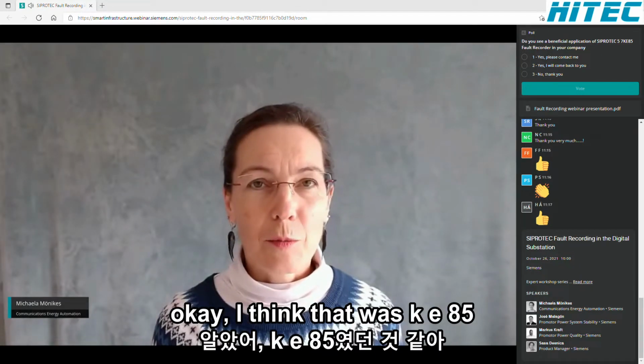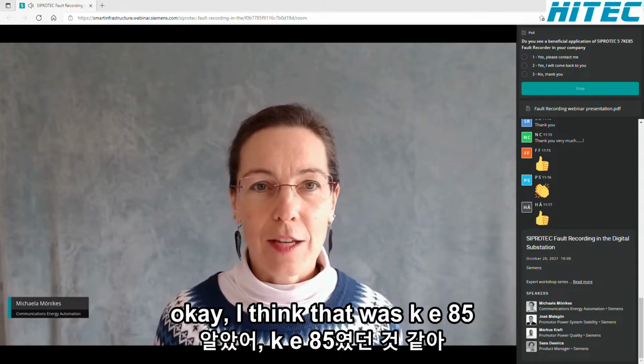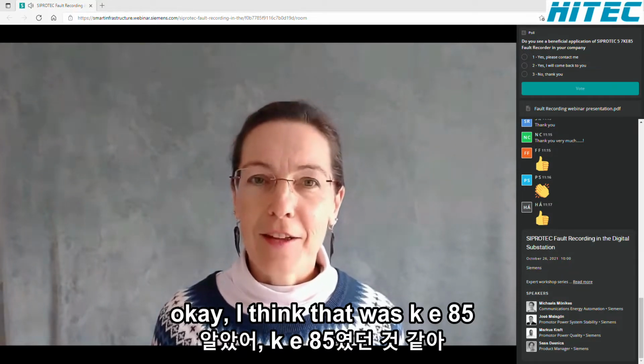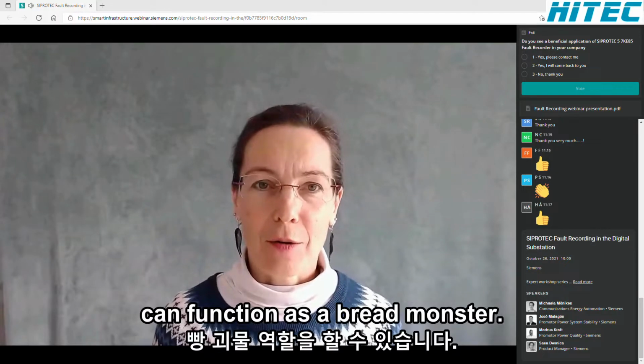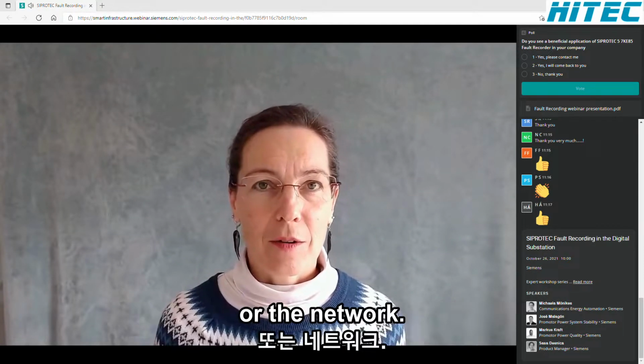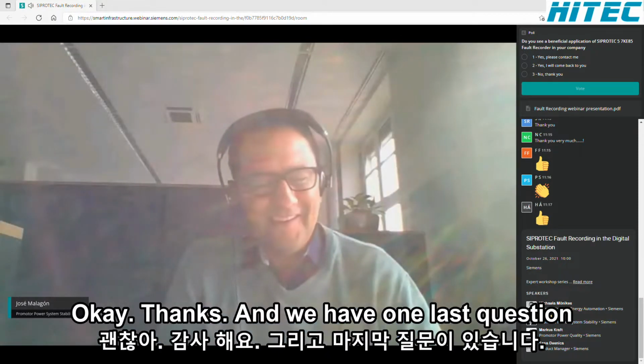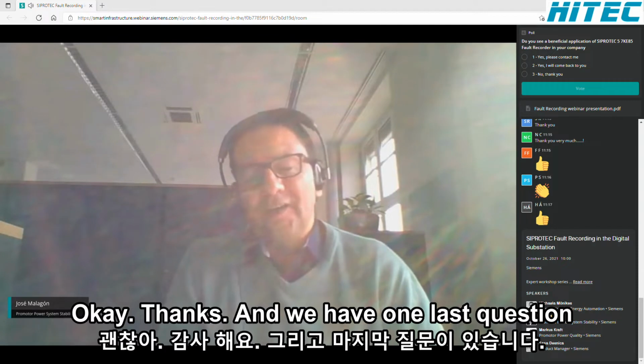Okay, I think that was almost the answer to the next question, because there was the question if the 7KE85 can function as a grandmaster clock in PTP to synchronize the merging unit or the network. Not yet. We need to use an independent master clock.